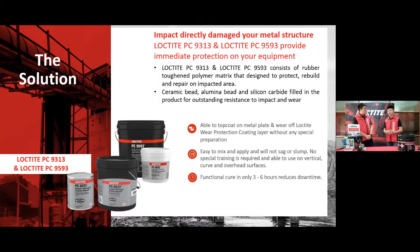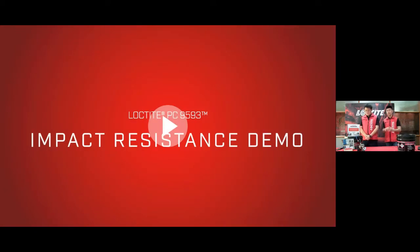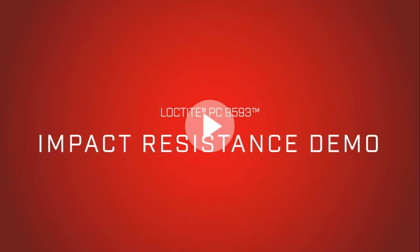Some of the key benefits are the same as our wearing compound: also no wear, easy to apply, able to apply on vertical and overhead surfaces without any sagging, and the functional cure for these products ranges from 3 to 6 hours. All right, I'll take this opportunity to share some of the performance of our Loctite PC 9593, so that you can have a better understanding of how this product works and performs against impact damage.